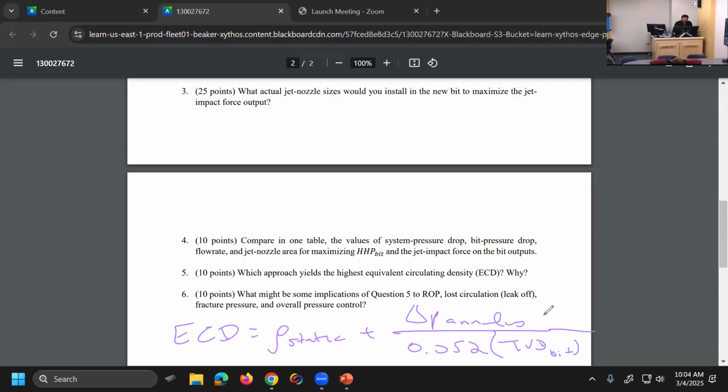You need to tell me which column of the table will impact this the most. I think if you look at the parameters, you will now see which one gives the higher value as you compare the table. This depends on what? Yeah, pressure drop in the annulus. It depends on the frictional drop in the annulus. Which depends on what? It depends on the length of the drill pipe, the length of the hole. They stay the same. They are the same for both cases.